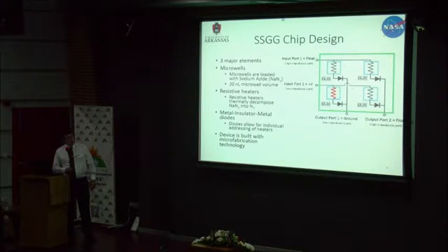Lastly, there's these diodes, and diodes are used for individually addressing each well. So the red resistor there is driven with the port conditions that are shown. These are my input ports, these are my output ports. I would drive this heater by applying voltage here, applying a float or a high impedance input here, ground here, and a high impedance float here. By incorporating the diodes, we can reduce the number of input pins for the device, which makes this device practically scalable.